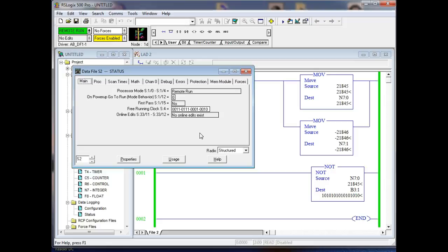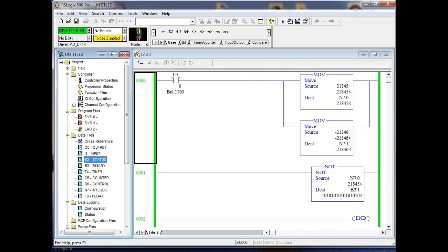Normally your index register is going to pop up on here, but the problem is that the 1100 doesn't use an index register. What'll happen is the main registers that you use usually pop up on the very front of the list. I forgot that. So what we would get is another line here that would show us the current contents of the index register.